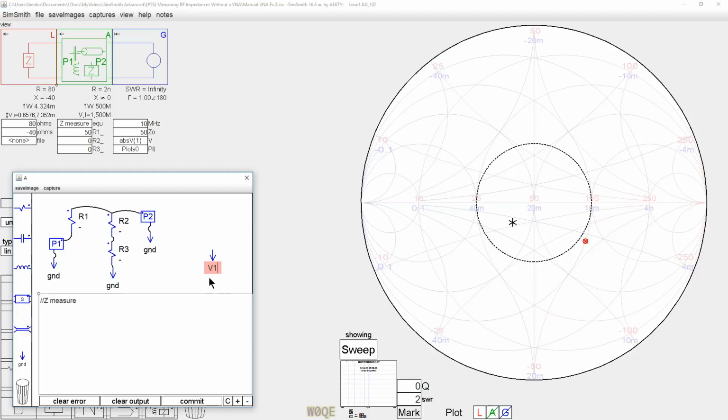V1 and V2 like before. Grab the label, or just point over it, the R key, rotate it. Control C on that, Control V. I didn't need it named R. Change this one to be V2. This is a little tricky to type, talk, and do everything at the same time. Okay. Grab it, bring it over here. And there's the circuit. Now we're going to do a couple things.